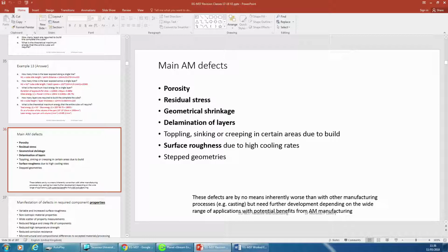You might be as high as a couple of thousand degrees for a very short duration of time, but although that cools, it means the entire surface has a high temperature. Each layer has a higher temperature, and you attach to a very cold base plate, and you have support structures possibly running down the sides, which means that you are literally clamping a hot object to a cold object, and as the entire thing forms, those stresses that are keeping it clamped are retained within the part. So you've got residual stress.